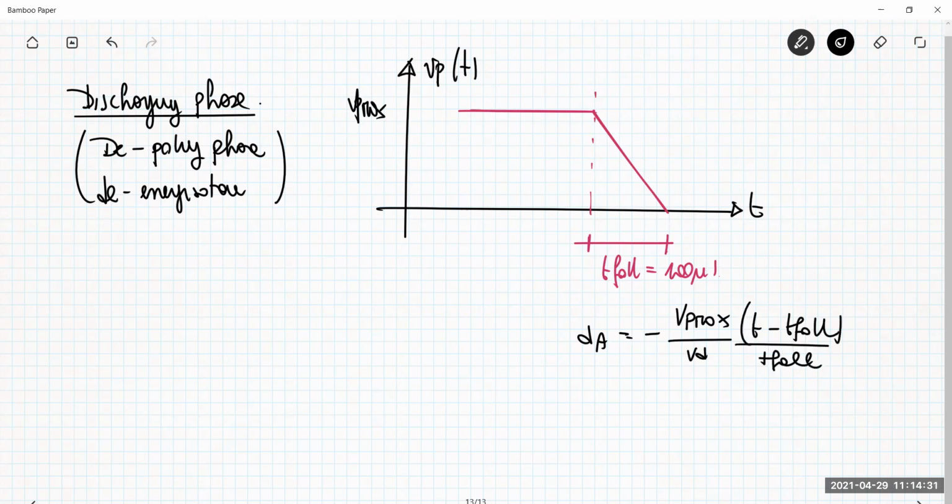So it's a duty cycle that decreases from 0.8 down to 0, the duty cycle of the high-side switch. In this region, we are operating the half-bridge converter in its boost operating region. So we are absorbing power from the load, and this power transits through the half-bridge toward the Vd supply.